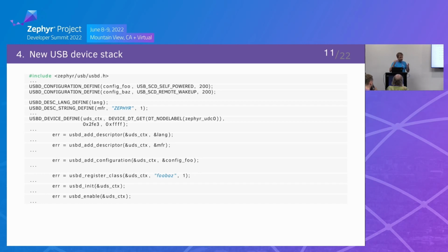For example, if someone attaches it to a host, they will receive an event that it is attached to the host, and can wait a specific time to give the charger device time to be initialized, or initialize a charger device if there is an interface to it. After this specific time, the user can enable USB.